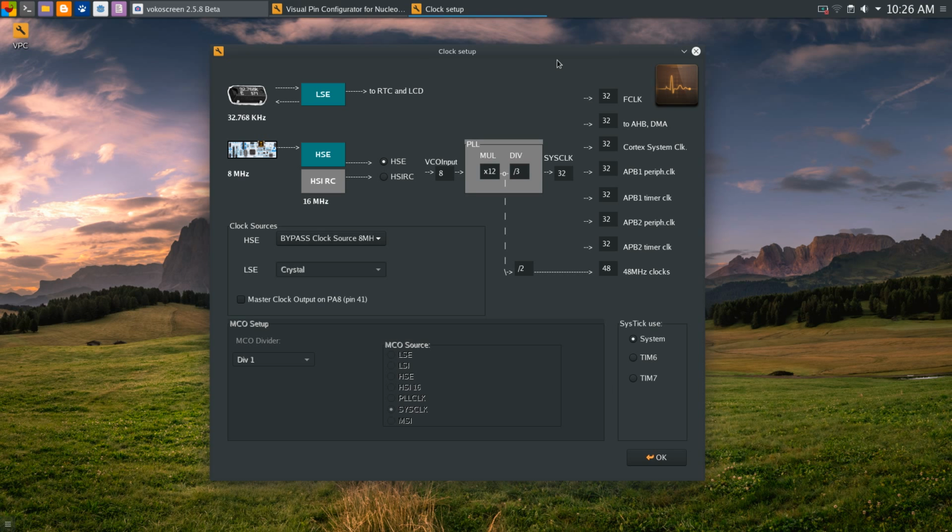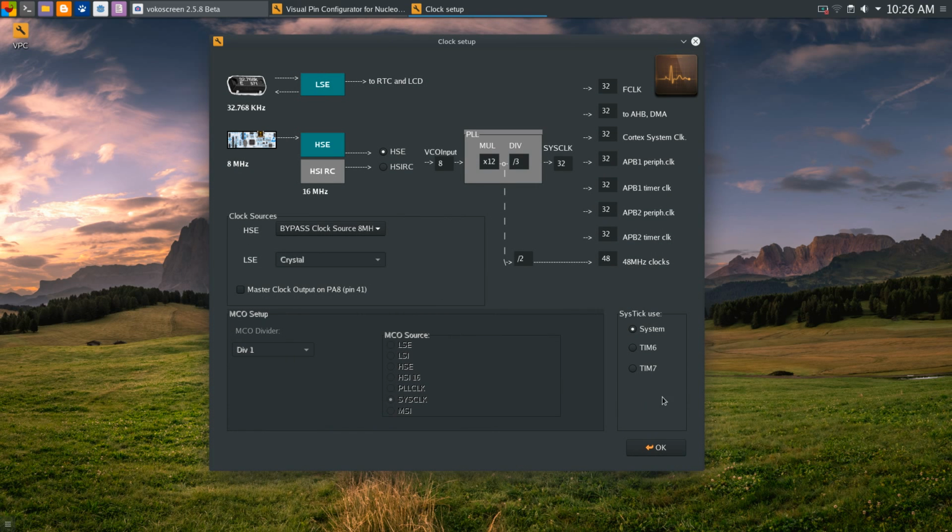What more you have here? It's about SysTick. When I learned LL drivers, low level or layer drivers, I don't remember exactly, SysTick wasn't functional. You had to combine HAL with LL to have a SysTick active.